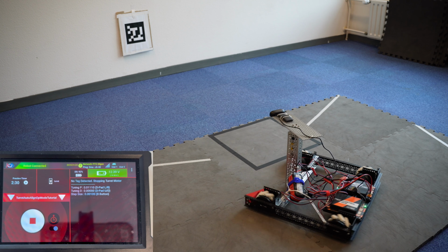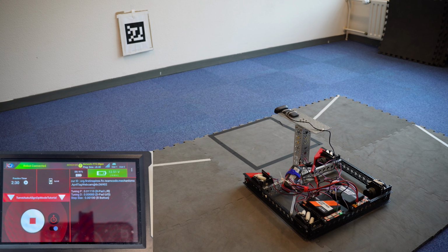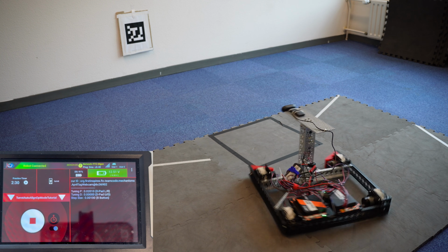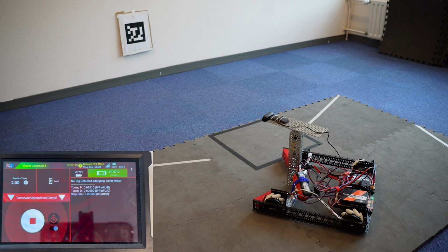And like I said, I won't be able to rotate super quick because my value won't increase. So let's try increasing our P again. Oops, that was D. What we want to see is the point where we actually start overshooting our target. So let's try, not 0.02, because we want to be out. There we go.